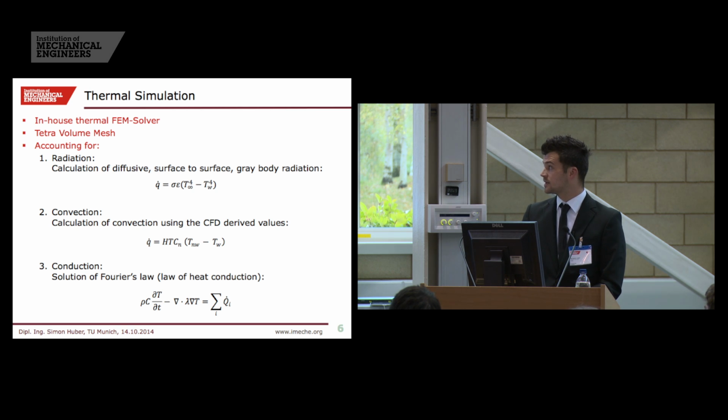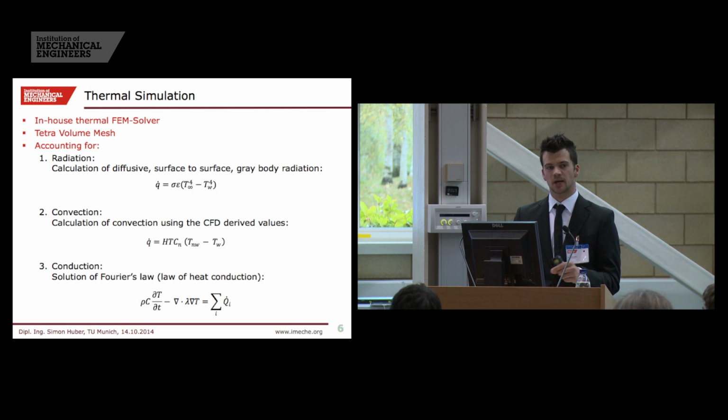The convection is calculated like this, and here we can see the heat transfer coefficient and the near-wall temperature, which is the temperature of the first cell, and this is where the CFD simulation comes into the model. And the conduction inside of the model is simulated with the law of heat conduction, Fourier's law.